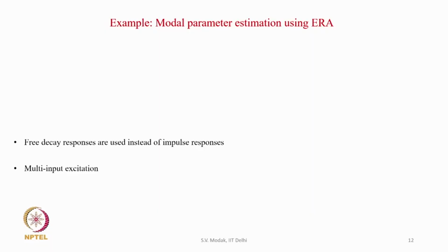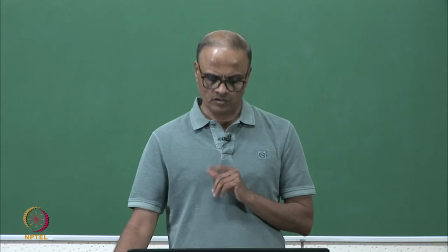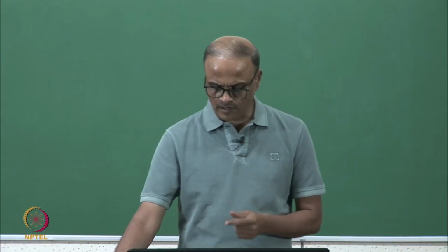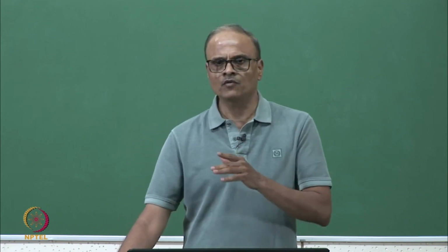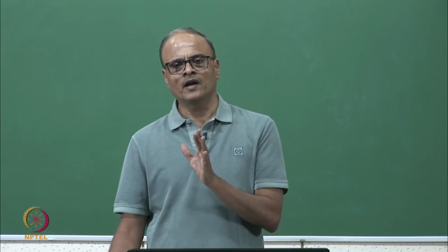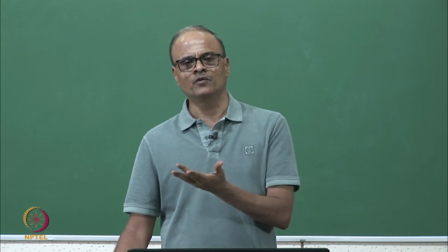and then we are going to use a multi input excitation. At multiple points we are going to apply inputs, and then use the resulting free decay responses to perform the modal parameter estimation. And then specifically we are going to use a band limited white noise excitation over a frequency range of 0 to 400 hertz. So, a band limited white noise is generated over this frequency range, and then that is used to excite the system, and these excitations are applied at test points 2 and 5 for a duration of 4 seconds. Then we stop the excitation after 4 seconds, and the system would vibrate freely after that point,